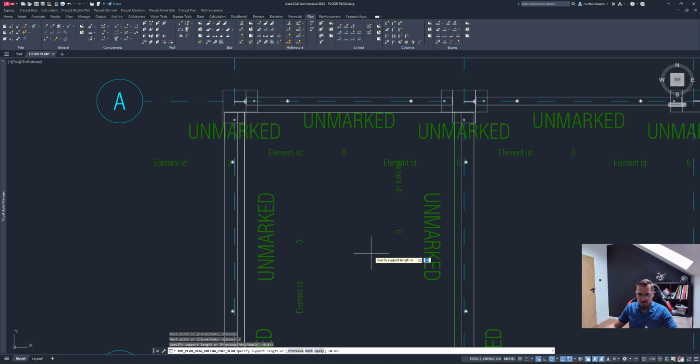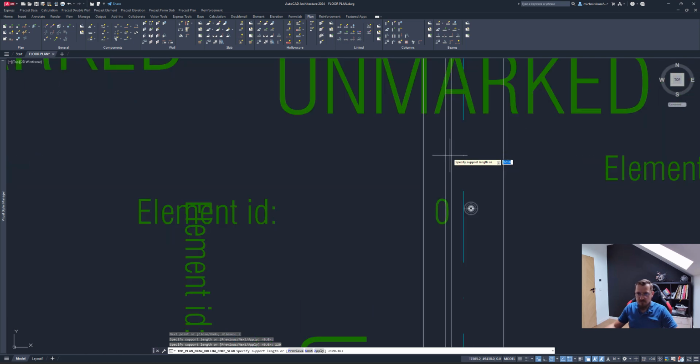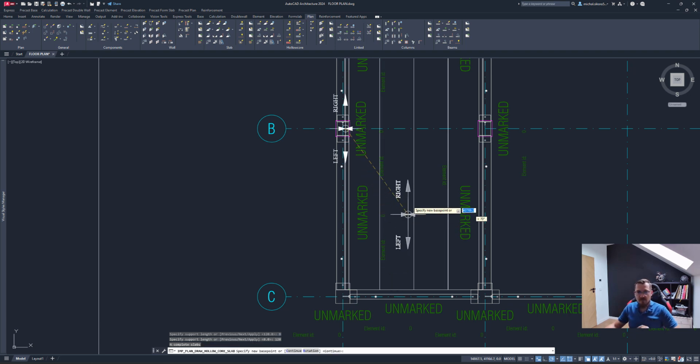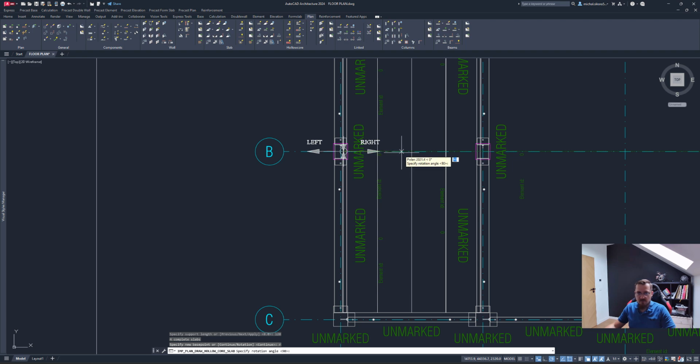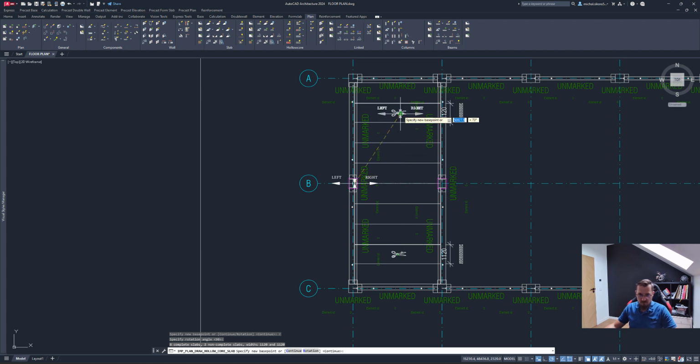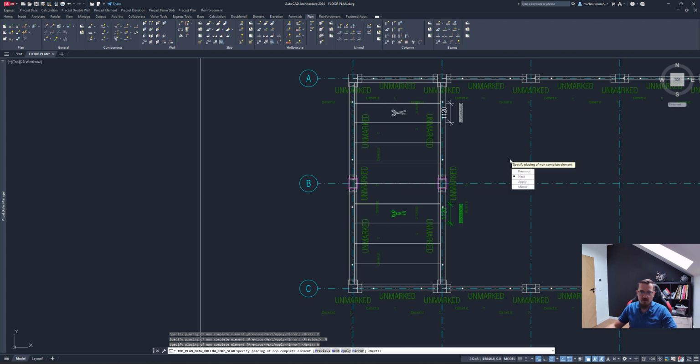Now this edge is highlighted green. Let's go and add that 120 mil support. As you can see, the line extended. Next edge, that's going to be 0 again, and 120 again on that last edge. I'll also rotate the hollow cores, and you can immediately see in the preview there will be some cut hollow cores to fit in as many non-cut hollow cores as possible. So I'll just accept that rotation, and I can specify if I want this cut element to be at this location, or just move it around to different locations. So you can specify that wherever you want that to be.